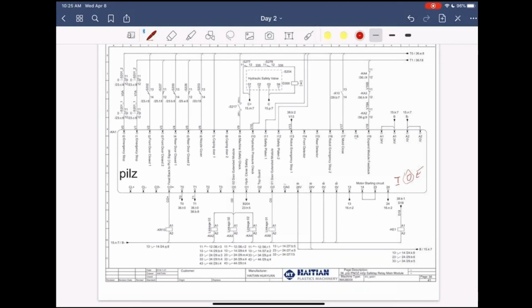The error is resettable by taking a jumper on I18 and OA0, just putting a jumper between the two with the power off, turn the power on, wait till the error clears. Once the error is cleared, you can remove the jumper.